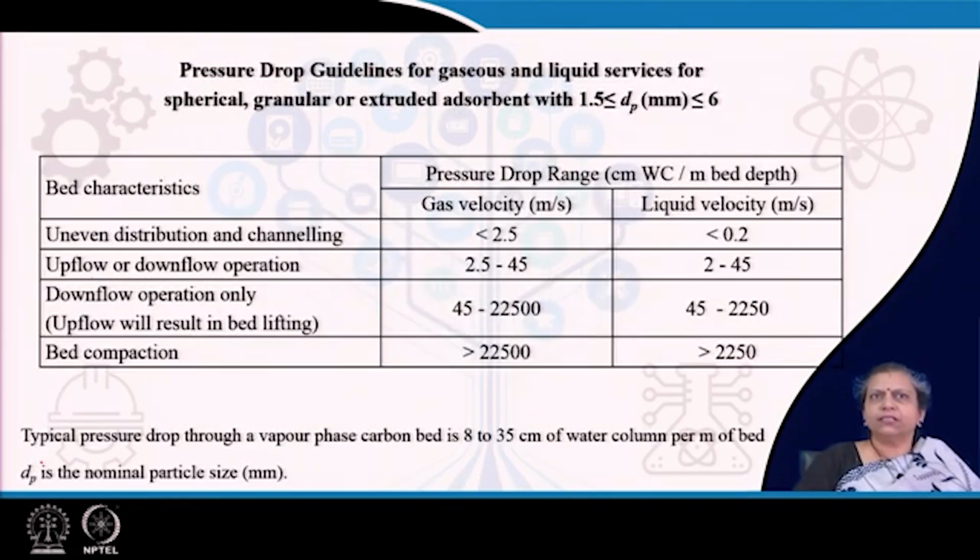So, usually there are certain guidelines. You must have found that during the entire course of the discussion on the design, I have given you several guidelines which you might consider, and also several checks. So, there are certain guidelines provided here for the gaseous and the liquid services using spherical, granular, or extruded adsorbent particles when the size lies within a particular range, and this size is defined in terms of the nominal particle size.